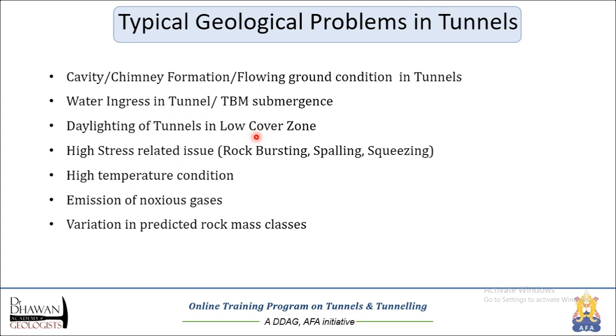These types of problems could be faced. High stress related issues, that is rock bursting, spalling or squeezing. This is normally experienced in tunnels which are driven through high overburden cover.